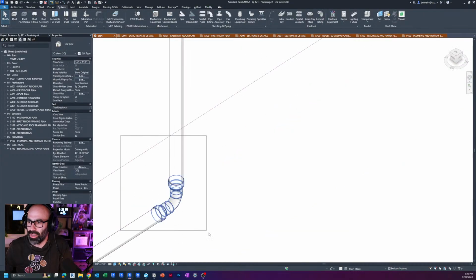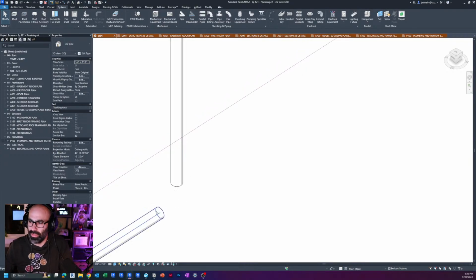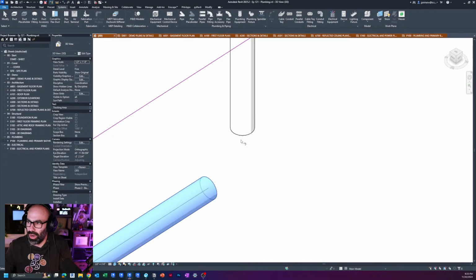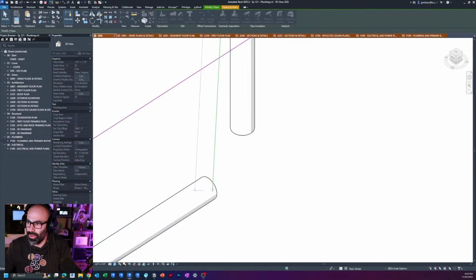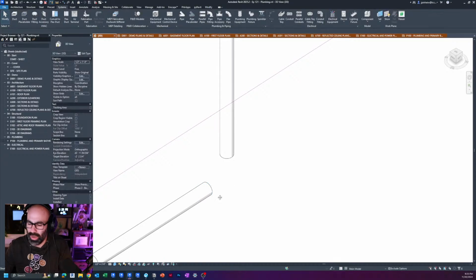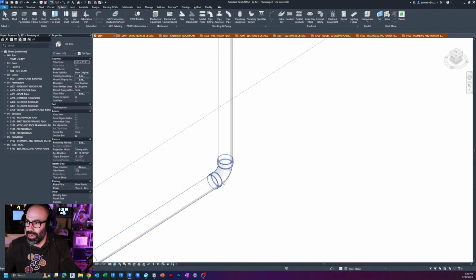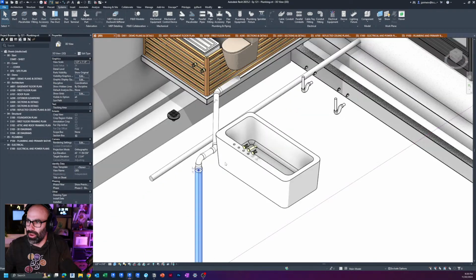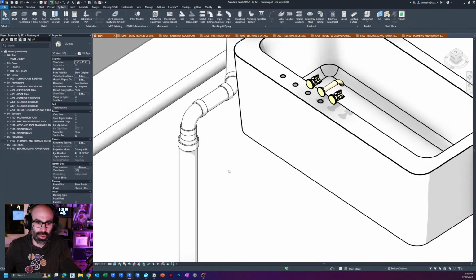But now all these fittings are kind of screwed up, so I'm just going to delete these fittings. And remember, I could trim it. So trim is TR. Or I could just grab it and pull it and look for the center and lock it. Of course, it won't find it now. All right, that's all right. We'll just use trim here. TR, and you can see now I've got a 4-inch here. Now the reducer's up here, a little more realistic there, right?